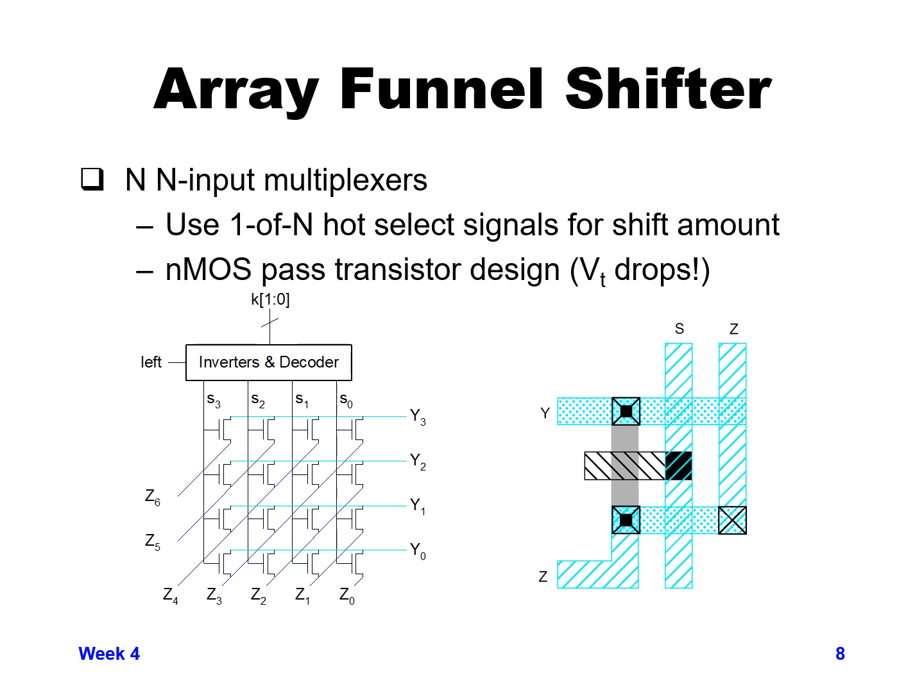So you can see each row of NMOS gates is basically performing a 4 to 1 mux function, because we have a select 0, 1, 2, and 3 going to each of the 4 NMOS gates. So only one of those selects is going to be high, which means only one of those NMOS gates is going to be on in each row, and it will then be selecting the Z value.